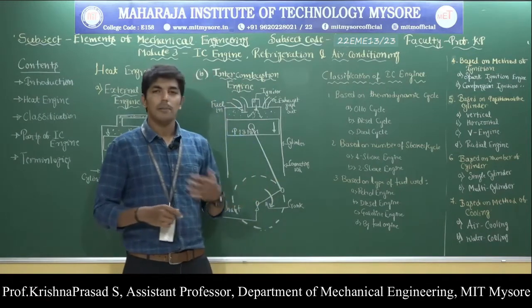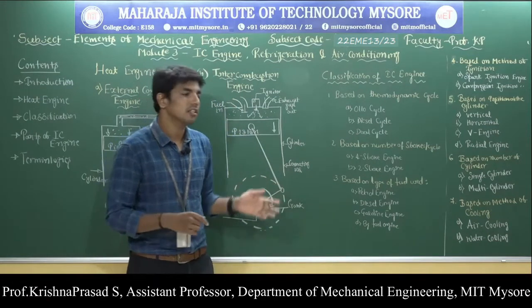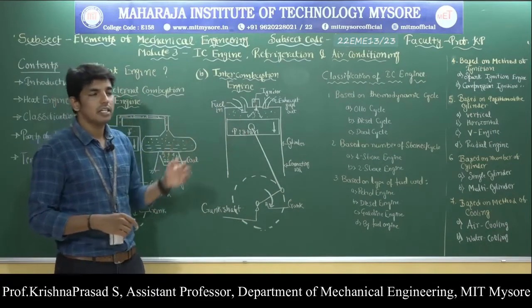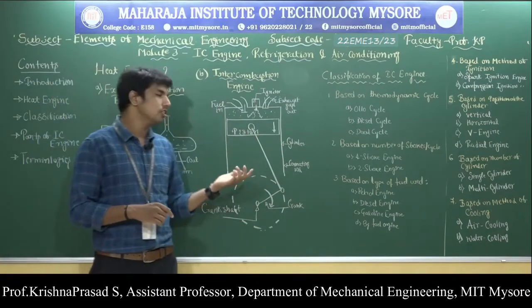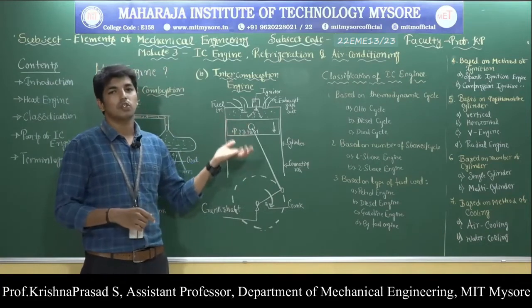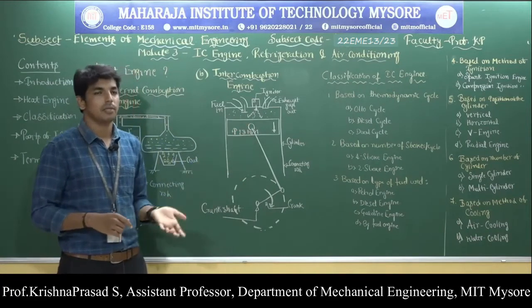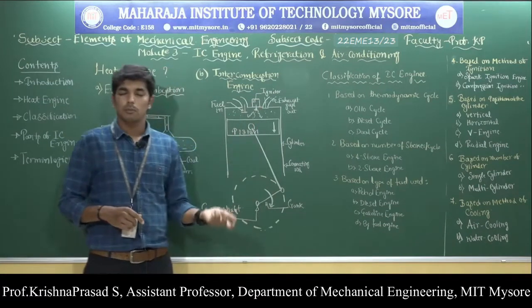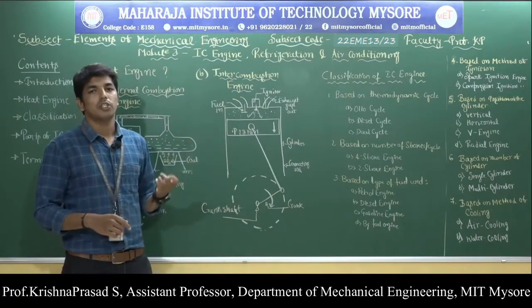So what happens in the suction stroke? In the suction stroke, the air-petrol mixture enters the engine cylinder. Then, in the compression stroke, the air-fuel mixture is compressed to very high pressure and temperature. In the power stroke, the air-fuel mixture burns, and hence high power is developed.